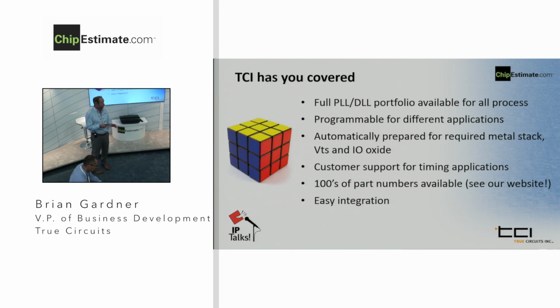And then the last, we try to make integration easy. So we typically provide all our IP as a single hard macro. We'll have decoupling, we'll have guard rings, we'll have keep out. You typically only have to hook up to a core power and a couple of timing domains. And really also we try to keep the commercial side easy too. So the real thing we want to do is provide something with support and make it as easy on you as possible. You already got a hard job to do just procuring the maybe up to 75 IPs that you might need for a typical chip these days or more.